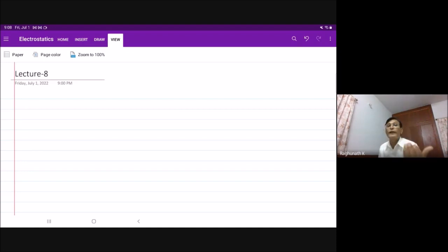When we apply this voltage as a supply voltage to the circuit, current starts flowing through different branches in that circuit. And these currents can be determined by knowing the volt ampere relations of different components in the circuit and the fact that the sum of the voltages around a closed path in any network or circuit is always equal to 0.